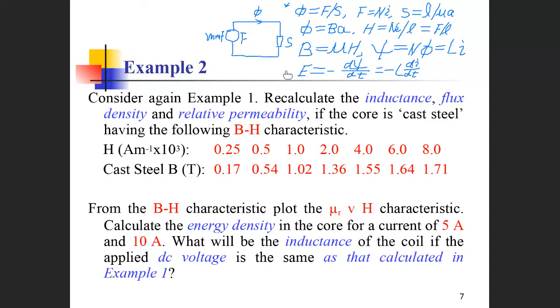So first, physically, we have a coil to which we apply a current I. The turn number of the coil is N. Then the coil has an equivalent magnetomotive force F. The coil itself has the cross-sectional area A and an effective magnetic flux path length L. It has core material, and that core material has permeability mu.